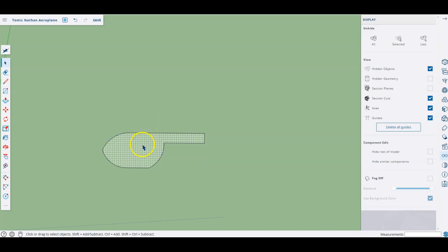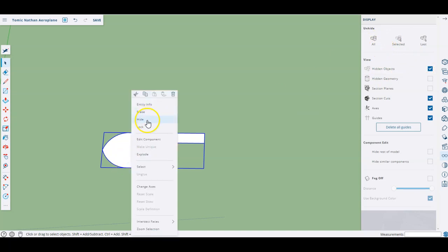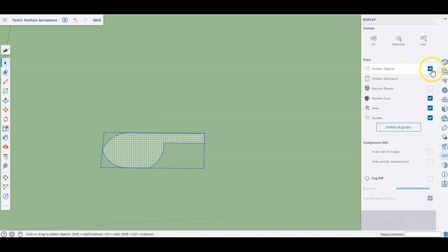As you just saw, I can click on it to select it, and that's where I could then use that selection and come back up to the top here and choose the selected objects and unhide it that way. So if you've got multiple hidden objects, you don't have to unhide them all and then rehide some of them. You can say, show me the hidden ones, choose the ones that I want to affect and unhide them. But for now, I do want to hide this, and I'm going to turn off the hidden objects as well just for the moment, so it goes away.